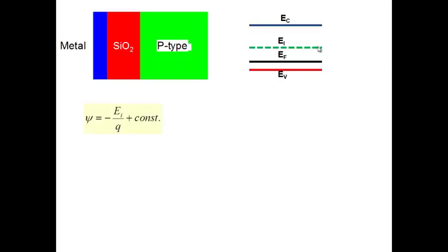This equation also people remember, np equals ni square e to the power (Efn minus Efp) by kT, right? I don't have any external excitation, and I'm not injecting anything, so I don't have np exceeding this. So Efn is flat, Efp is flat, and both are equal.